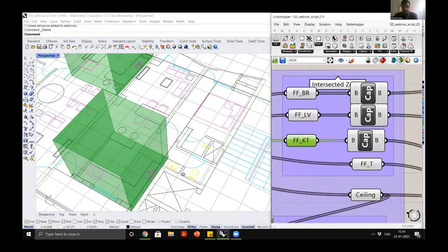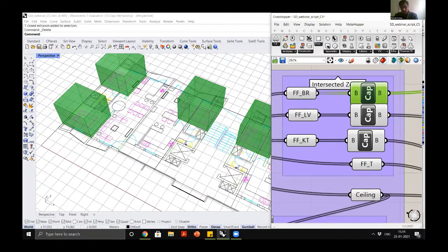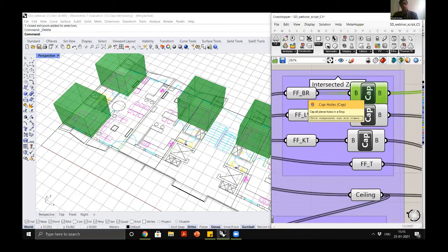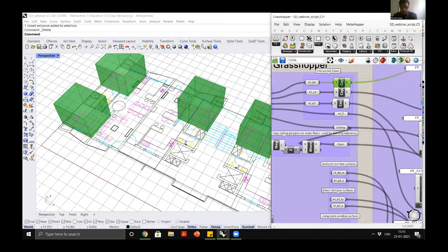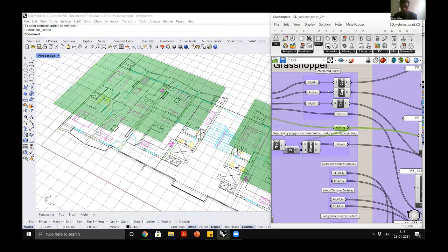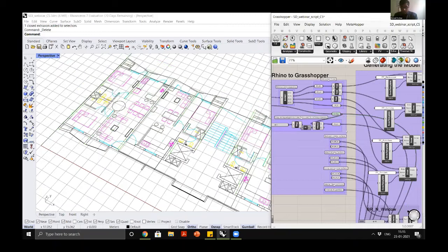This is a function that I had to introduce because there were some issues in the geometry, so they were having a number of holes in them. So this command cap will essentially fill the geometry again, and it will make it a completely volumetric zone. So again, I have now recovered the intersected masses for all my zones, and now I am ready to start inputting them into zones. Before we proceed to that, we need to understand one more thing, that is the boundary